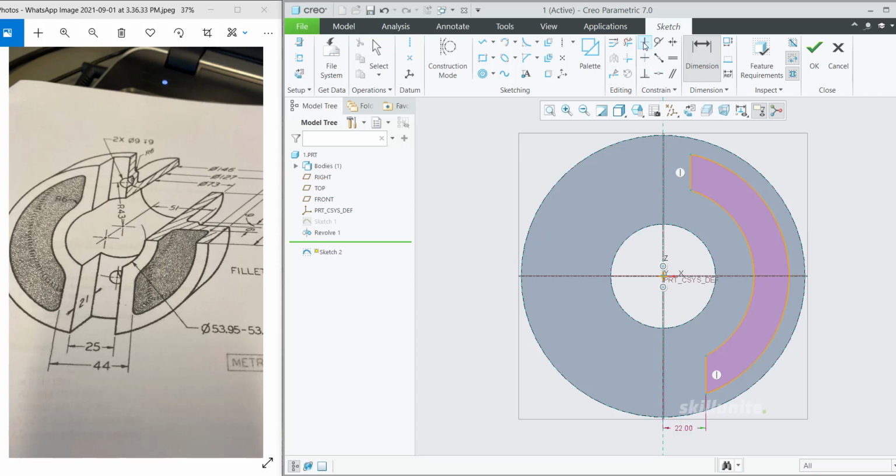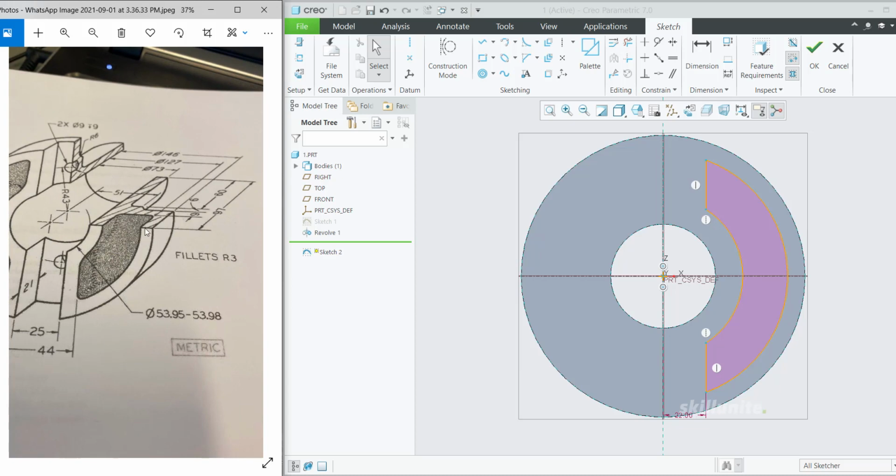So next you can use this vertical, select this point and this point, make it on the same axis, like a collinear kind of thing. So then we need to limit this distance and we need to limit this also. So how you can limit that means we need to know the distance. So for knowing it you can come over here. So the outer diameter is 127. So select that and click on diametrical option. So mention 127 for it.